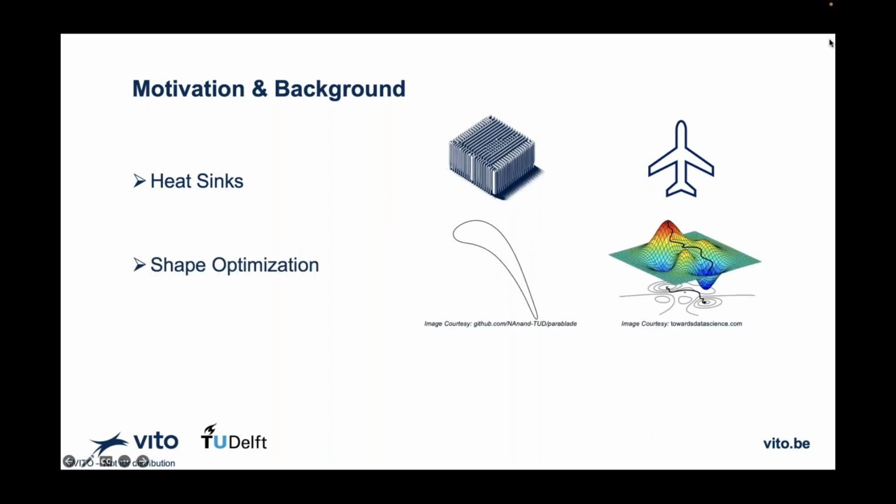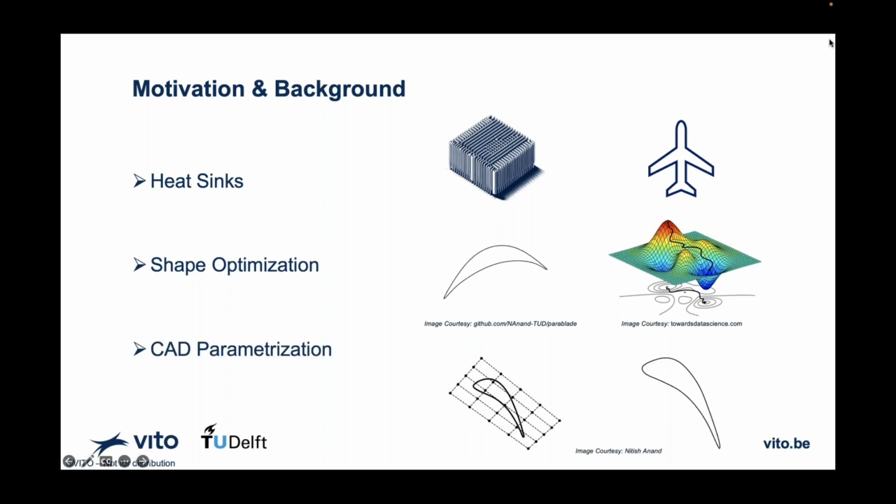One way to push the limits of heat sinks is to use shape optimization, and this is possible using SU2. This will help us improve the performance, extracting maximum heat transfer while minimizing operational losses. This is conventionally done with FFD boxes, or free-form deformation boxes, in SU2. But one limitation is that we have limited control over our design surface, and that doesn't allow us to impose geometric constraints very well.